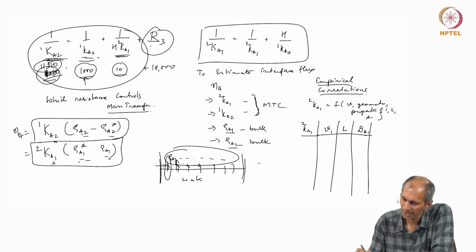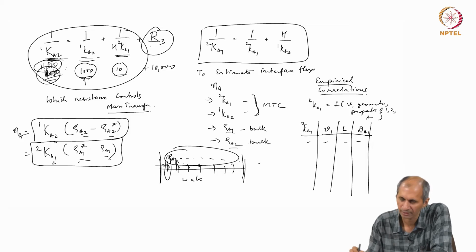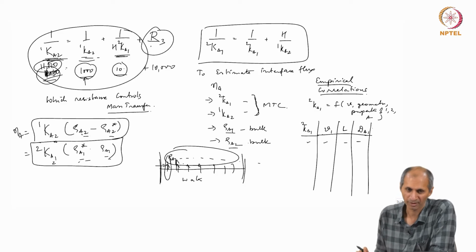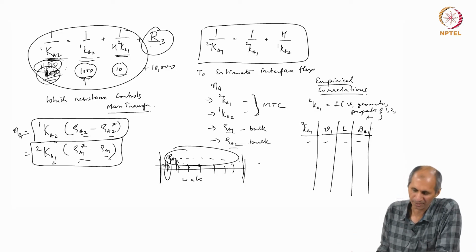So, what I have to do is I have to measure the mass transfer coefficient at every set of conditions. I will have different velocities of air, I will have different lengths, I will have different dA1. What is the meaning of varying dA1? I am saying I will vary dA1 in different experiments. What is the implication of that? What does it mean? We are changing the compound, we are changing A. So, with different diffusion coefficients, we are doing the same thing with different chemicals to see if there is a correlation with the property of the chemical itself, so the diffusion coefficient itself.